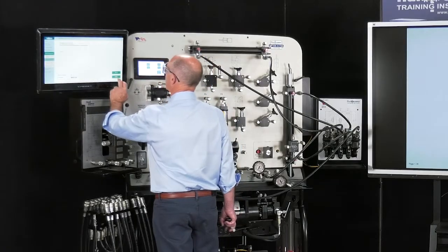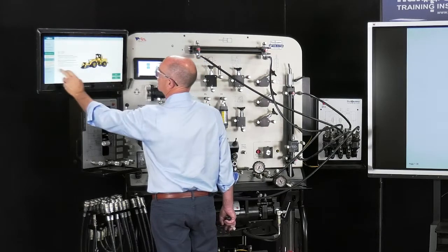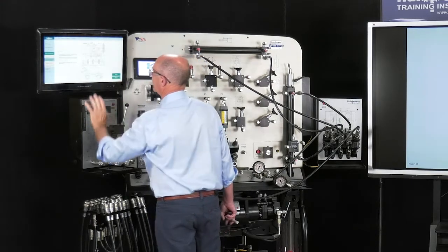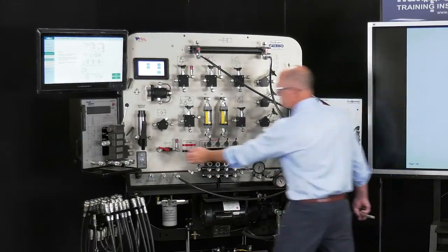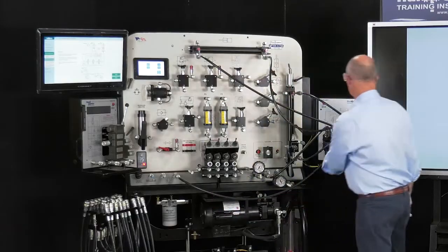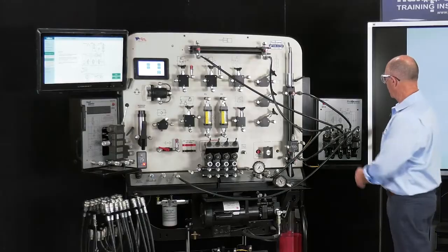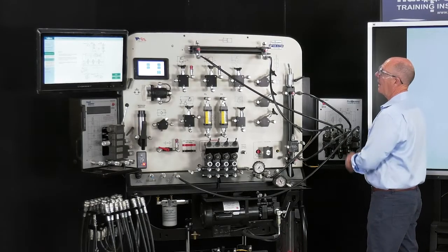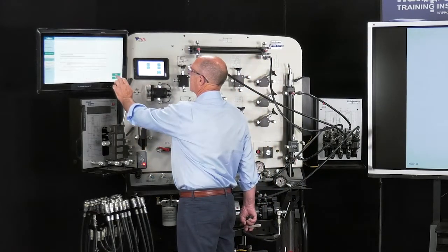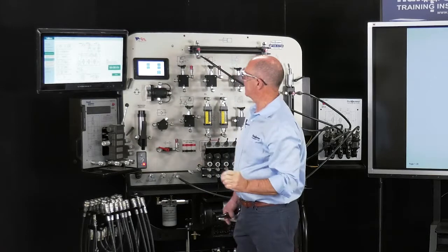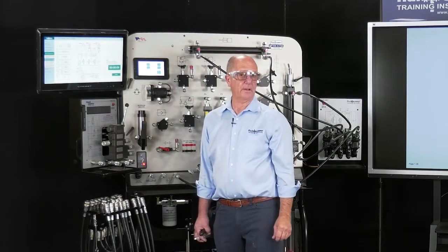Let's look at that. So I'm going to go back, and I'm going to finish this activity. I'm going to go back to raise lower, and I'm going to now just go through this activity. As we said, so let's restart, and let's revisit with this again. I'm going to raise the load, and as you can see, the load is holding. That's where you want to start. All right, now, as we said, when I go to the next screen, it will enable the fault, which means now this time, the cylinder is going to be drifting.